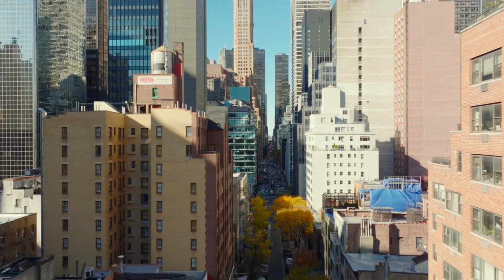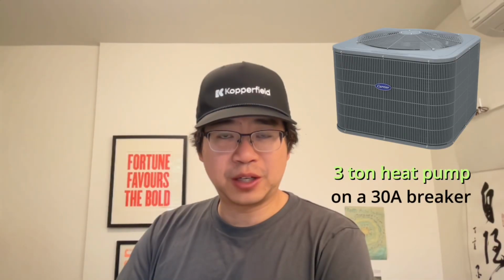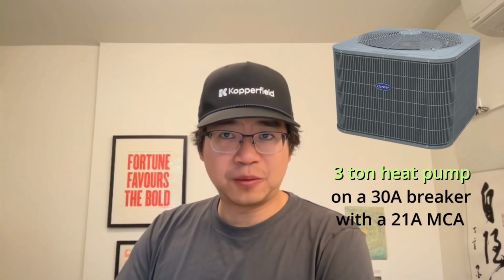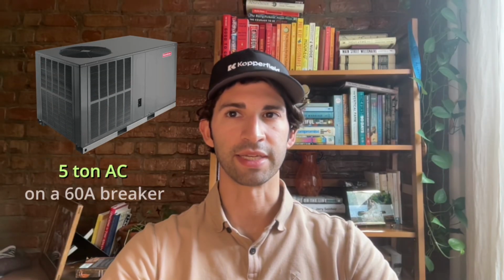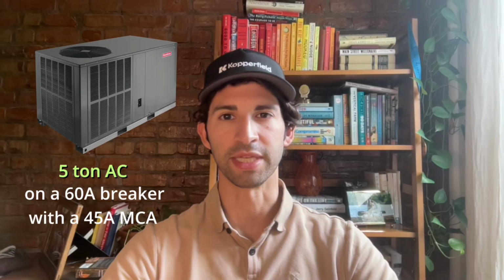So let's dive in. The job was for an office in New York. The office already had a 3-ton heat pump on a 30-amp breaker with a 21-amp MCA. The office had a normal amount of receptacles and other loads. The electrician was asked to add a second AC unit for the office, a 5-ton AC on a 60-amp breaker with a 45-amp MCA. And all of this was on a 150-amp subpanel.